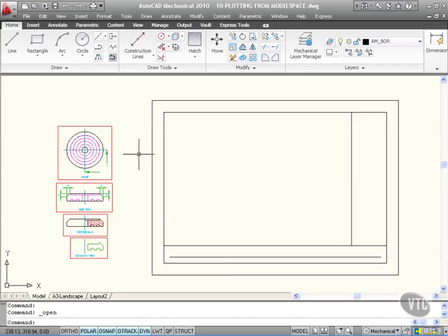So I have 4 scale areas here that need to plot within this particular title block. Now this particular title block here is an A3, an ISO A3. That makes it 420 millimeters along the bottom, 297 millimeters along a vertical edge. So what we're going to do is place these scale areas onto our drawing title block.